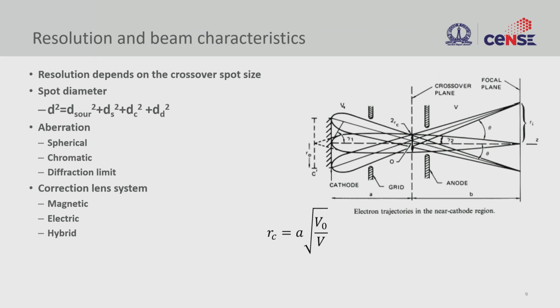The next thing is about the resolution of these beams. What actually determines the resolution? In optical we said lambda over NA, times K. Here we discussed NA, we discussed lambda, and also K, how the process determines the resolution. So let's look at what determines the resolution here. First of all, it's a pencil beam, a very sharp beam.